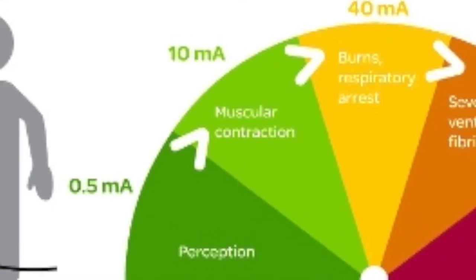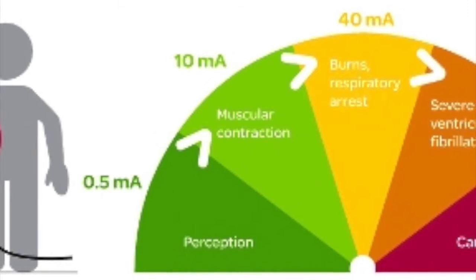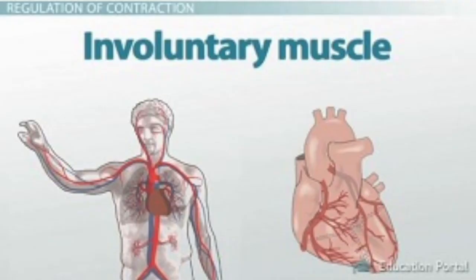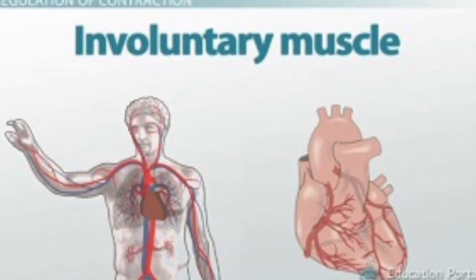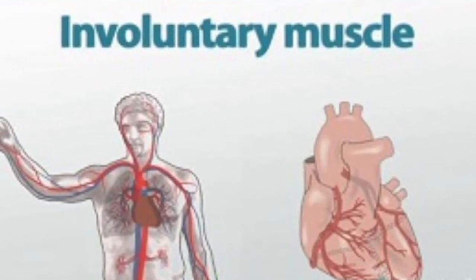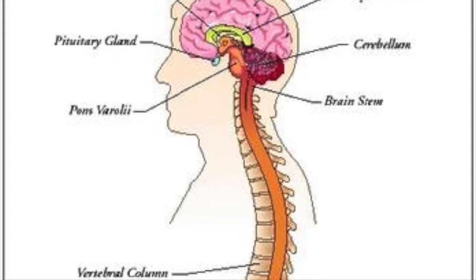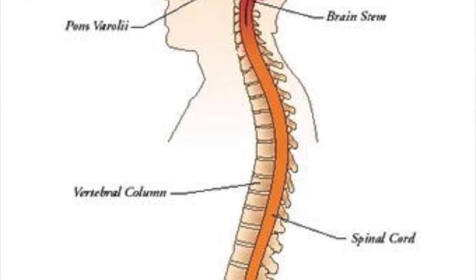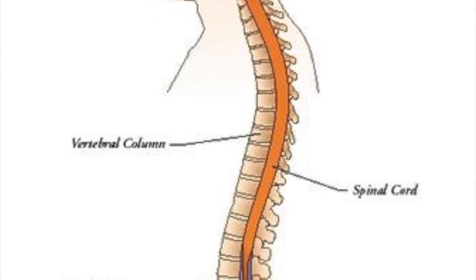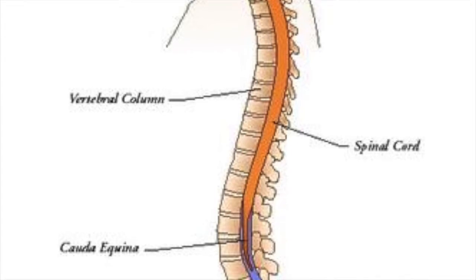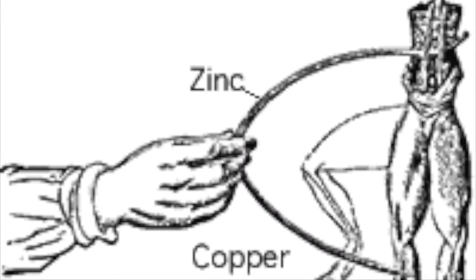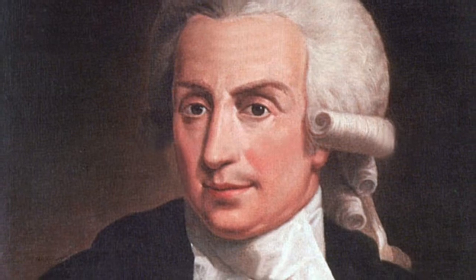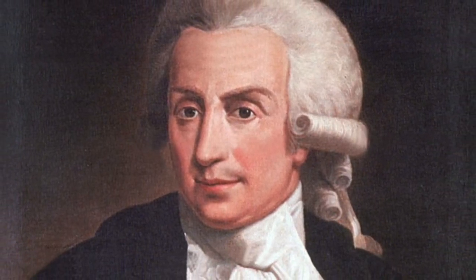A final indirect danger associated with electricity is associated with one of the physiological responses of the human body to an electric shock, and is the hazard of being involuntarily moved by the electric shock. The body's muscles contract when they receive a small electrical signal from the brain through the nerve system. External electrical signals, such as those resulting from an electric shock, can also cause muscle contraction, as demonstrated in 1791 by Luigi Galvani and his experiments with frogs and electricity. These externally caused muscle contractions are involuntary, and in many cases can be violent.